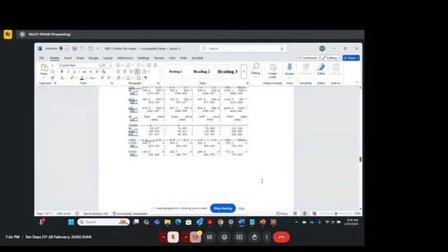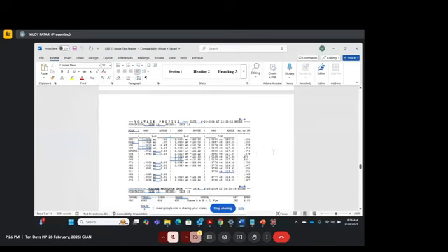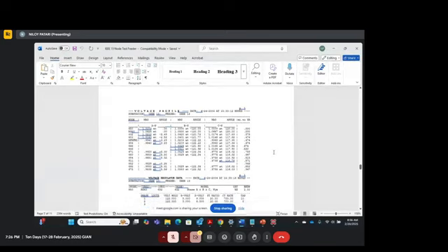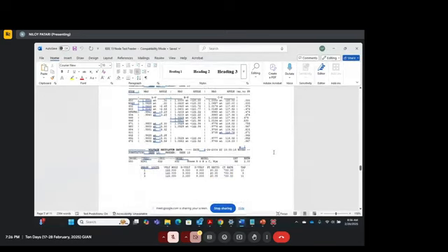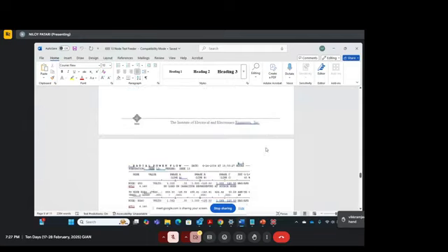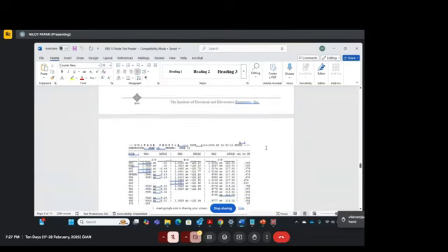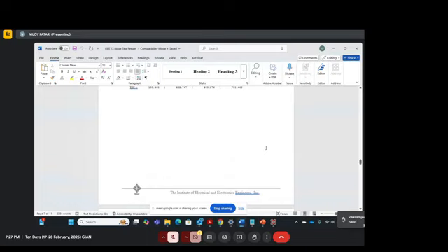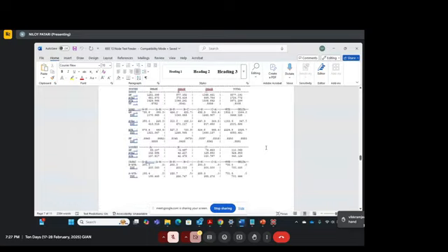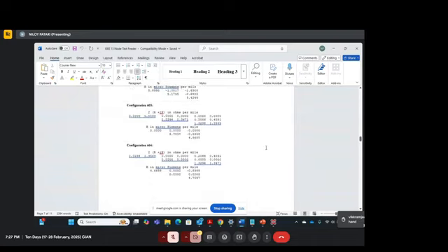So these power flow results will show you the voltage profile, right? It shows you how the voltages look, what the voltage regulator data is, and at the end of the day, how the taps look for each of the voltage regulators and all of that. The reason for showing this docx document is that whatever is written in this document, you have to exactly copy that in OpenDSS, right?